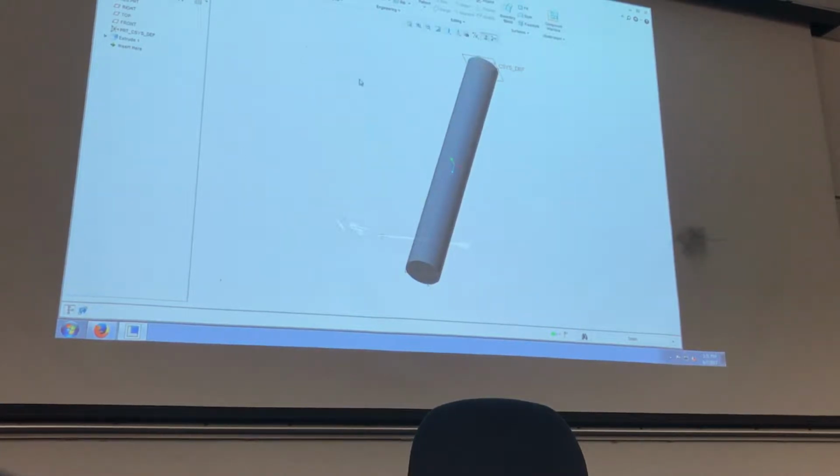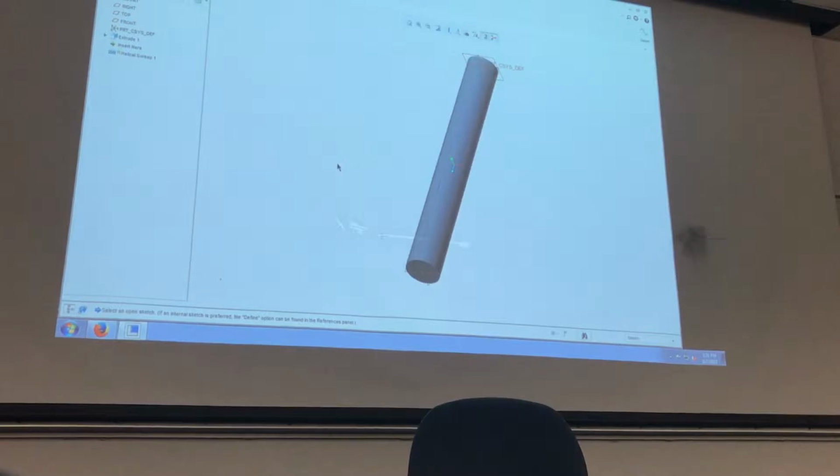All right, so the next thing I want to do is the helical sweep. Under here, under sweeps, click on here, it's got a sweep and a helical sweep. The one down here has got the blend and rotational blend. But this is where you're going to start up in here. We want a helical sweep. When you do the screws for the Stirling engine, do not do the helical sweep. It takes a lot of memory and a lot of calculation to go ahead and create that rotation going up in the helical.